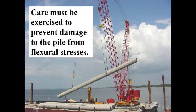so later on the structure will be positioned. Coming back to the discussion of loading the piles, if you notice, the cables are positioned at certain locations on a pile, and if it's not done properly it will be easy to crack the pile, the body of the pile, and it wouldn't serve the purpose. From your structural courses you can do some analysis and realize what's happening and why we need to pay attention to the location from where you will be putting the hooks around the pile in order to move it.